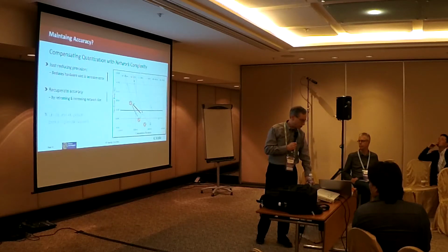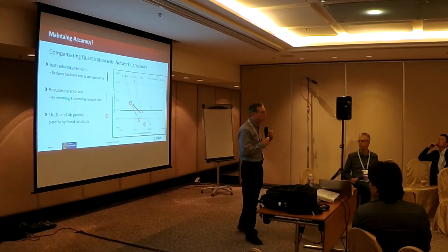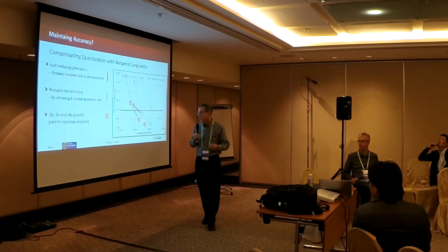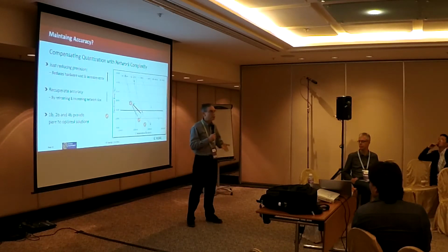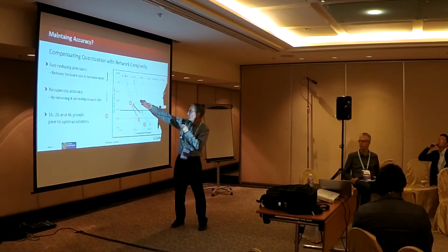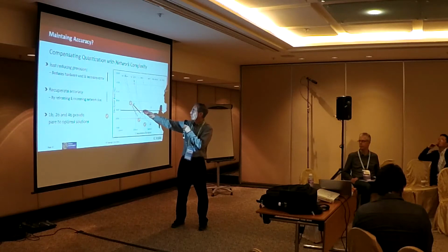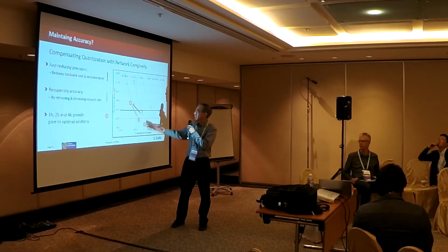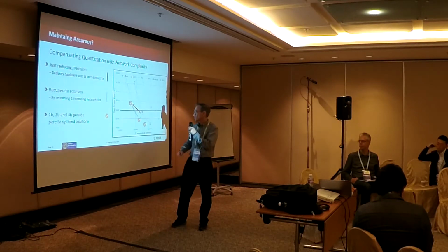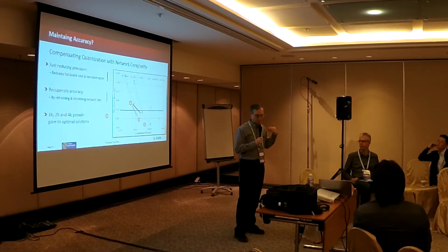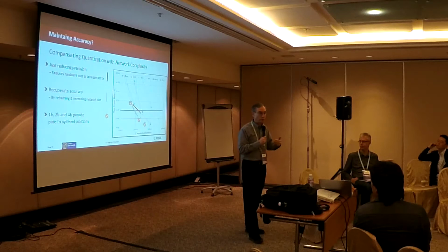And then the obvious question comes in, gee, if I'm going down in the number of bits, doesn't my accuracy go down? The answer is absolutely, your accuracy goes down. But the good news is that by increasing your network size, you can obtain the same level of accuracy. Here's an example of an int2. You get a particular performance with the same amount of logic. You're going to get lower performance with a binary network, but by increasing the network size, you will be able to increase the accuracy to obtain the level you want to achieve.